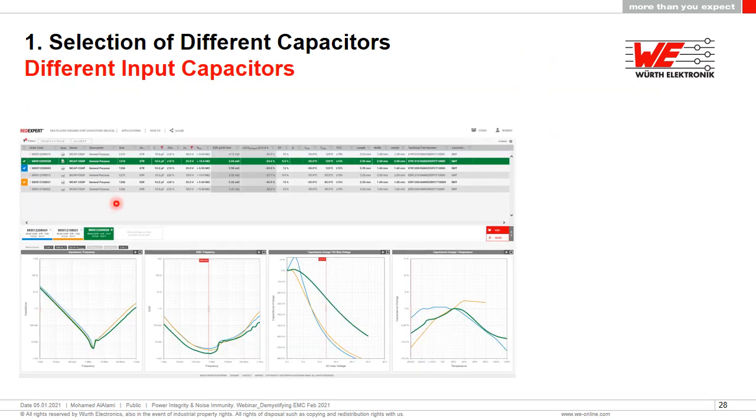We can't discount MLCCs, and as I say before, MLCCs do have a place, but for me the MLCCs are there to complement. I can still get a substantially high level of bulk capacitance from a polymer, and I can add some extra MLCCs to give me the higher frequency rejection capability at a lower value of capacitance. But again, in this case, we are comparing apples with apples. So this is 10 microfarads, it's an X7R component.